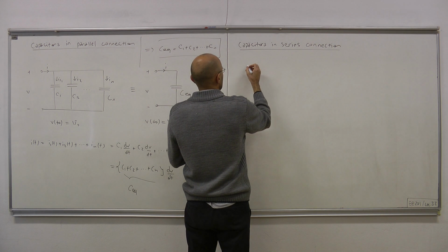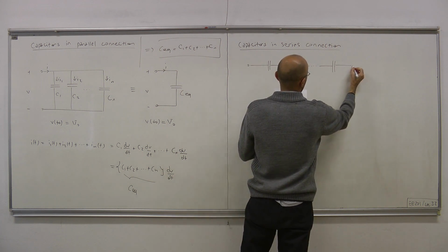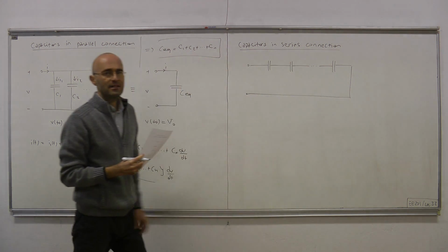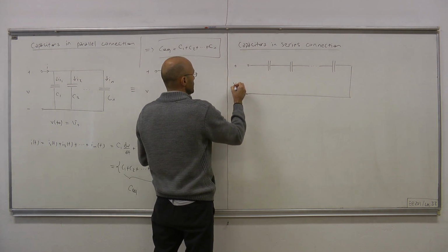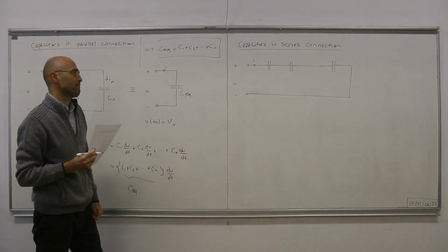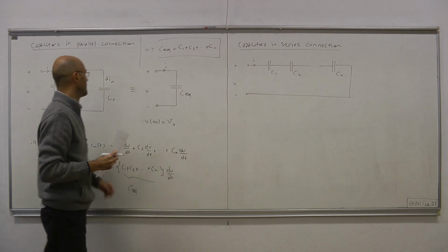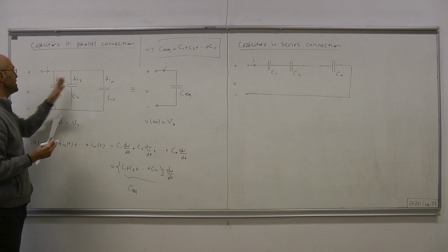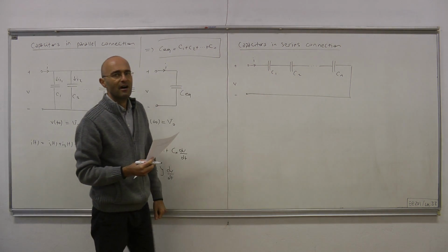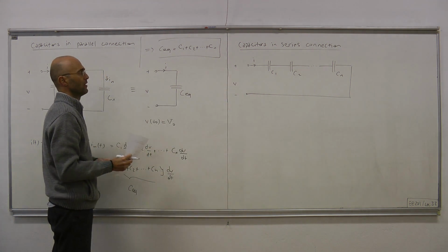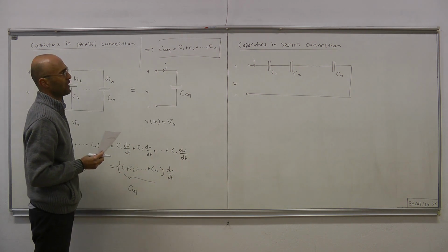Okay. Now, this is the case that we deal with. We have n LTI capacitors connected in series, and by doing so we obtain a one port whose voltage we denote by V and whose current we denote by I. Let the capacitance of the first guy be C1, the second guy C2, and so on. Now here, they all shared the same voltage because they were in parallel, but each could have an arbitrary current. Here we have a dual case. They're allowed to have arbitrary voltages because KVL puts no constraint on them like it did here. But since they're in series now, they must share the same current. It must be the same current that's passing through all.